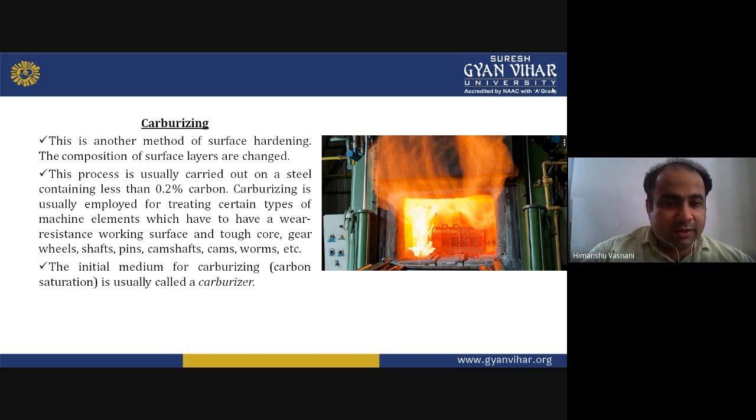Carburizing is usually employed for treating certain types of machine elements which have to have a wear-resistant working surface and, secondly, a tough core, like gear wheels, shafts, pins, and worms.